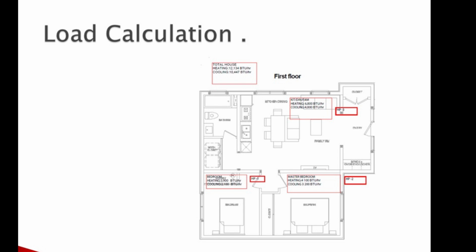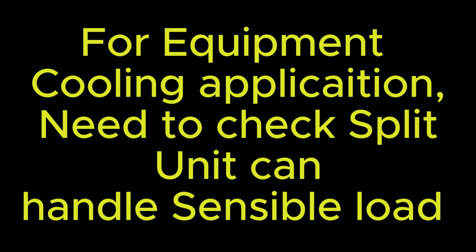I hope you have watched my video on what a split unit is. Therefore, ensure your split system has sufficient capacity for the worst-case scenario. You can simply request the performance data for each split unit and check if it provides enough capacity at those temperatures. If it's an equipment cooling application, you should have the breakdown for sensible heat and latent heat load. You have to check your equipment can handle the sensible load.